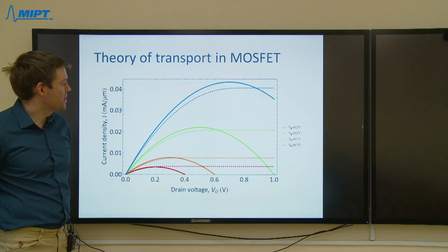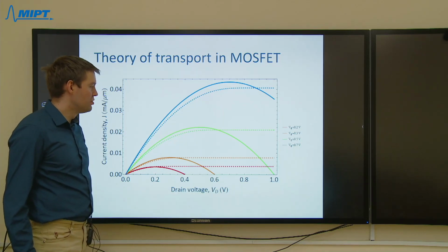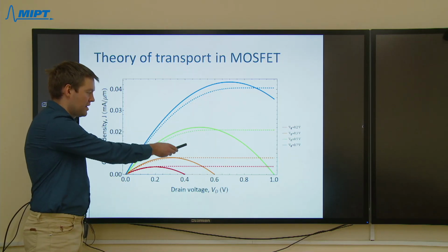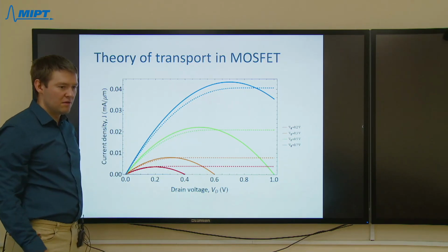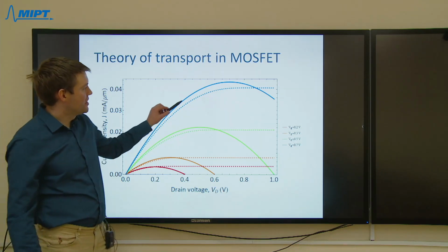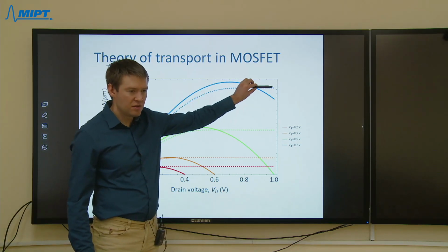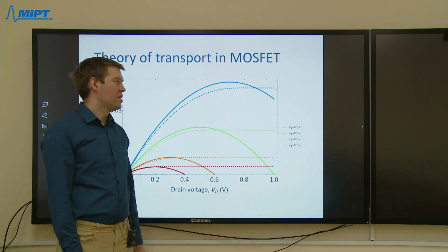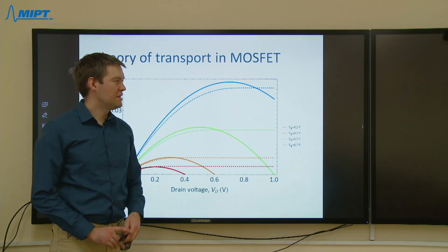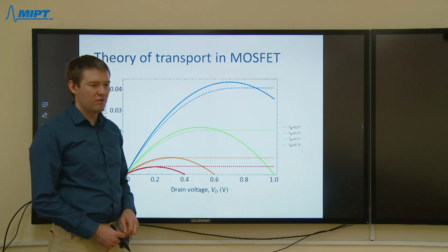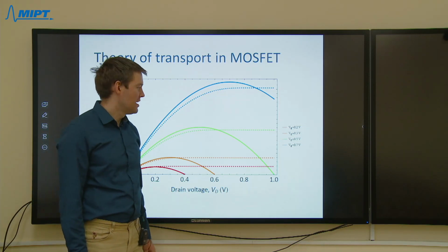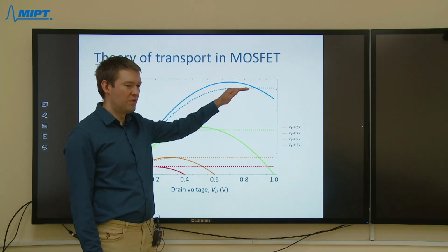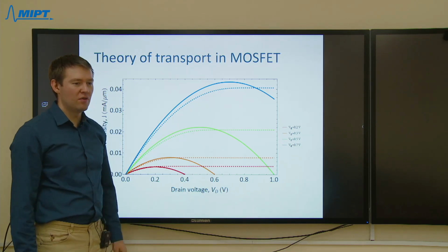Moving a bit forward, I would like to show that the true current voltage characteristics look like I show here with the dashed lines. So they move upward and then saturate to almost a constant value. This is the prediction of the true model, which is based on full consideration of charging effects. Indeed, the current can grow no more when we apply very high drain voltage.